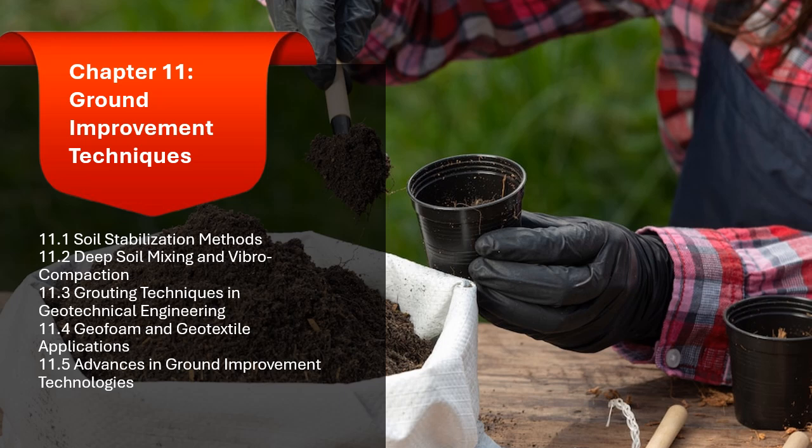1.5.2 Deep soil mixing and vibrocompaction. 1.5.2.1 Innovations in deep soil mixing (DSM). Deep soil mixing (DSM) is an advanced technique for improving the strength and stiffness of weak soils by mixing them with binding agents such as cement or lime at greater depths. Recent innovations in DSM focus on improving the efficiency and precision of this method, making it applicable to a wider range of soil types and depths.